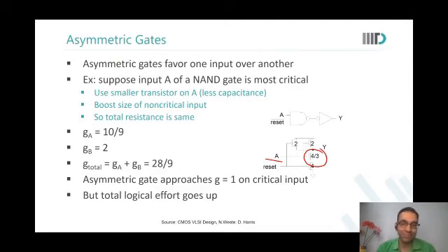Okay, so you have upsized the reset also. Yes. Otherwise it would have been 2, no? In a regular NAND gate, you would have put both the NMOSes sized 2. So the overall area you have increased, but the delay you have reduced.